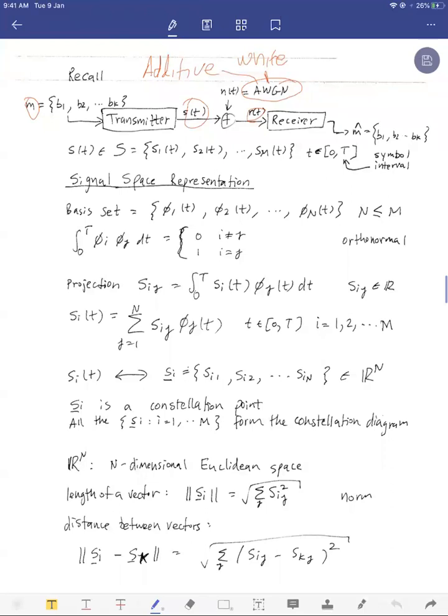From what I remember, you square the Fourier transform and then you integrate or something? Yeah, so this is okay when you have a deterministic signal, like if I give you a cosine or a sine. A random process is a little bit different. It's more of a statistical or stochastic quantity. So what we do when we have a random process is we look at the autocorrelation function, and then we take the Fourier transform of that. So the power spectral density is actually the Fourier transform of the autocorrelation.